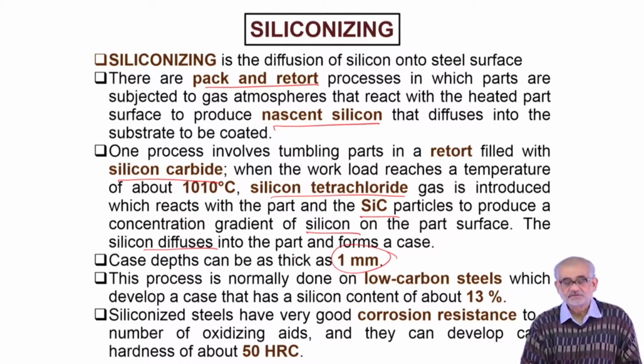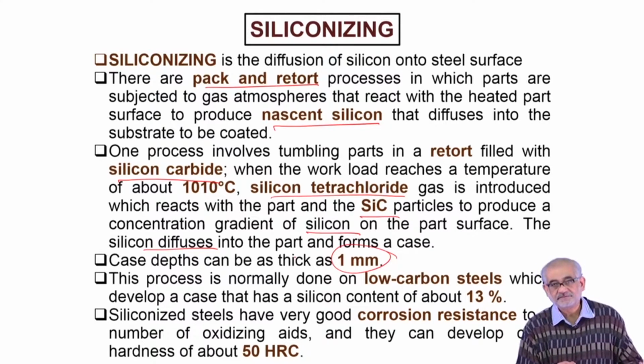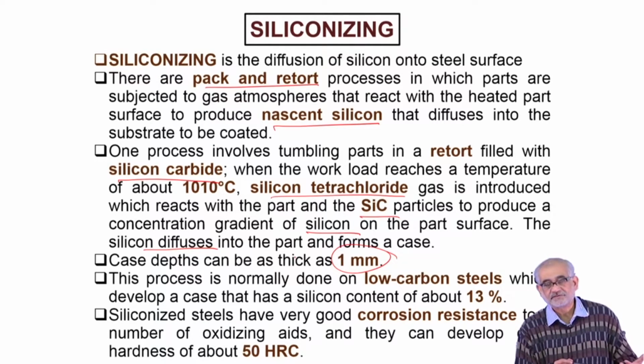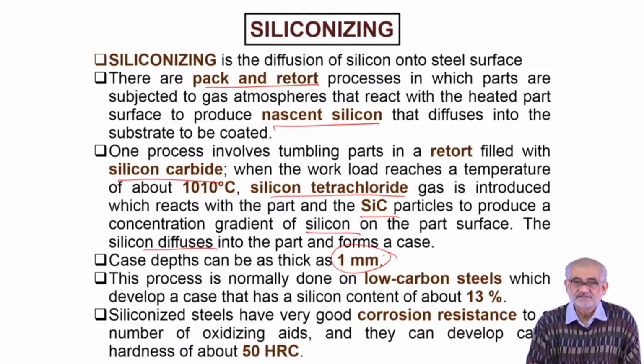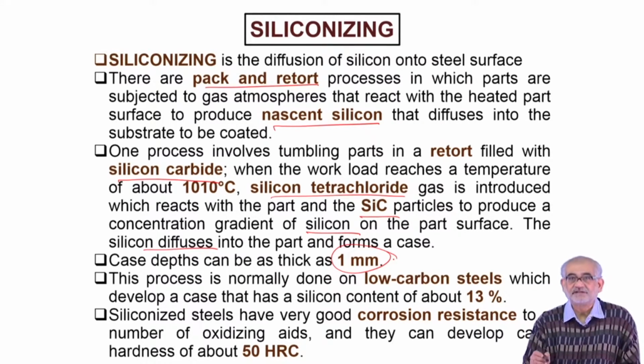So we are talking about in case of aluminum coating, we understood that we are talking typically a few tens to few hundred micrometers of aluminum rich layer, but in the limit it can go to several millimeters, but usually silicon rich layers are less than a millimeter, purely because the silicides that form instead of aluminides are actually slightly more complex in crystal structure and also form slightly more brittle layer.